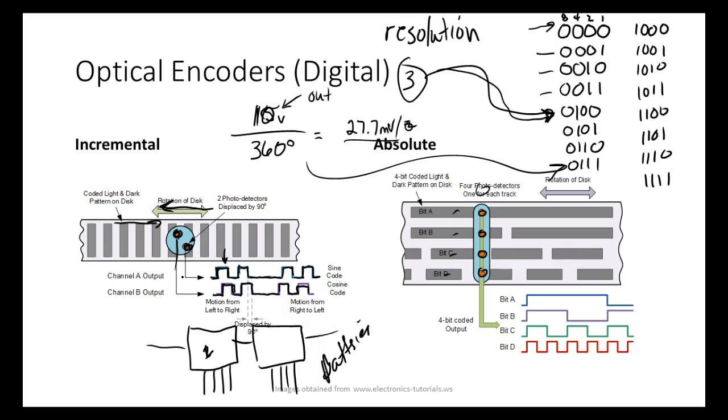When you take sensors, we would actually show you the circuit. The basic circuit can do that, but we don't need to understand that. So we have what we call up-down counters. We'd have a sensor that says, okay, if this one occurs first, count up. If this one occurs first, count down, right? And now we can move what? In both directions. So the robot's got to have that.